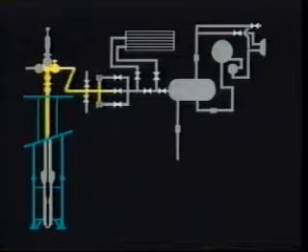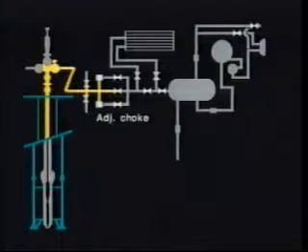We now turn our attention to some of the practical aspects of well testing, specifically the control of flow rate, measurement of pressure, the required surface test equipment, and finally a few aspects of test design. The control of flow rate during a well test is usually achieved at the surface through the use of chokes. In this drill stem test system, for example, 2 chokes are located in parallel in the floor manifold. One is an adjustable choke, the other a positive one. Flow is directed through the adjustable choke initially to determine the suitable choke size for the desired flow rate. Then a proper size insert is placed within the positive choke to maintain the constant rate. Flow is then directed through the positive choke.